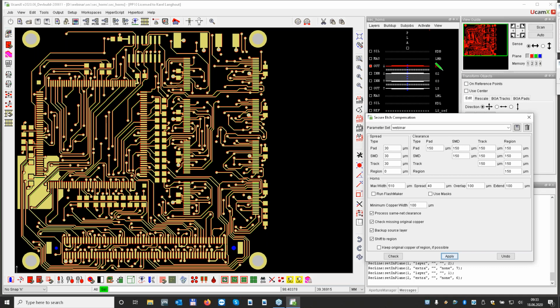No, you don't need to do a markup. It's looking at pads, SMDs, tracks, and regions. The regions are of course a certain aperture, the tracks are draws, SMDs are boxes or rectangles, and pads are round, circular pads. So the SMD is the SMD. The markup is already inherent in the data, so there's no need to do a markup. That's good.